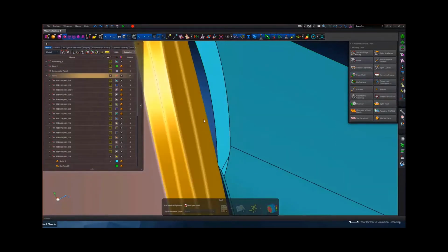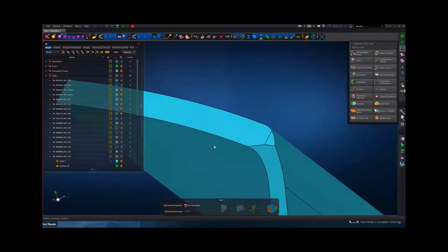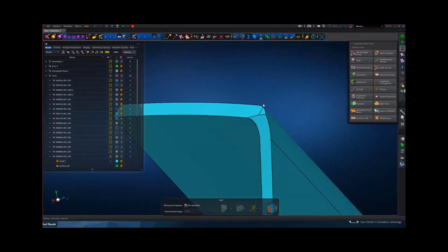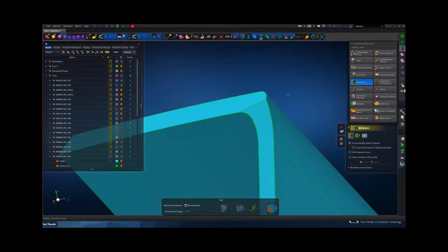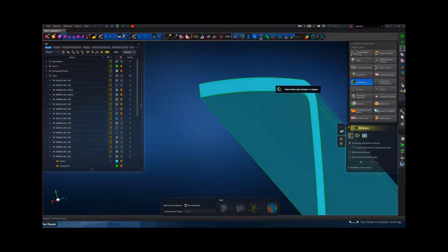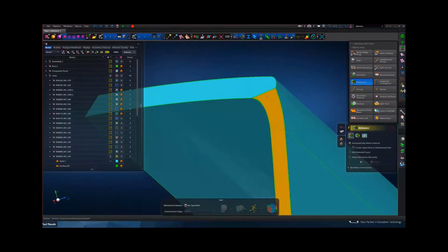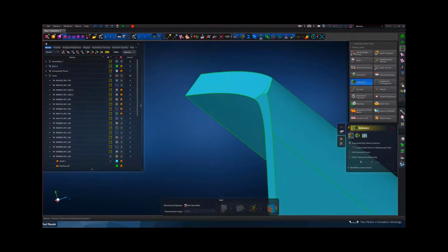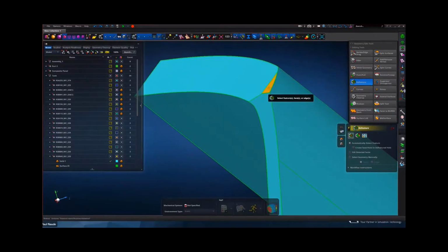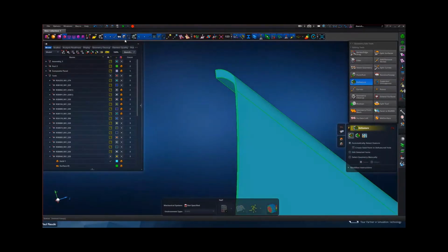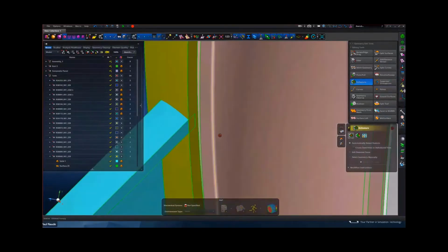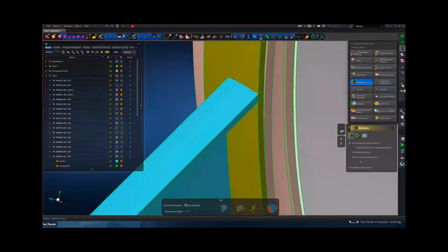So it might be better if we first hide these solids and get rid of these unnecessary features first. Again, we could remove them using our defeature tool like that. What that does is look at the logic of the remaining faces and see if it can find a logical solution. If we're essentially deleting this face, it can't leave a hole in there. It has to be able to extend the remaining faces to get to a result like that. Okay, so that was definitely one way, but in this case, that doesn't make those two faces match yet. We actually see that the one is now penetrating the other. So that's not really a problem.